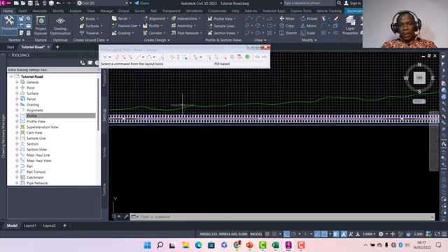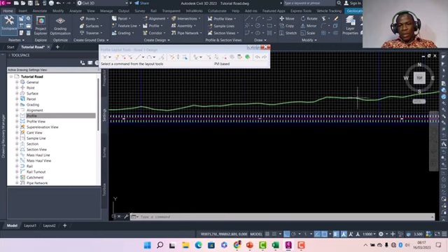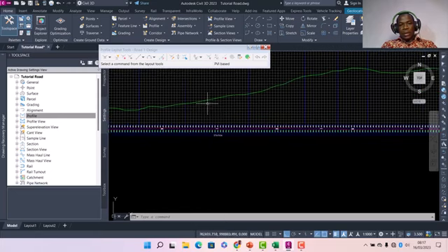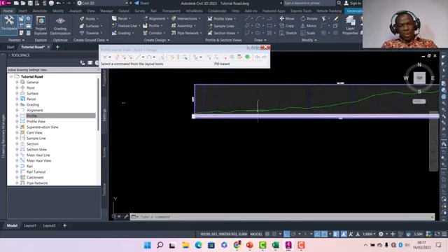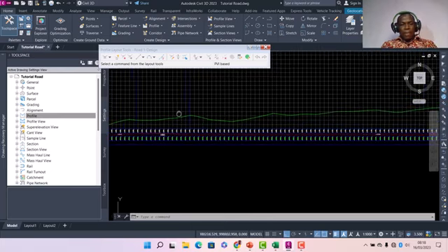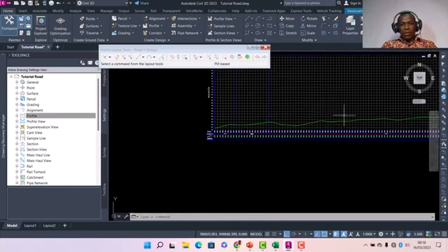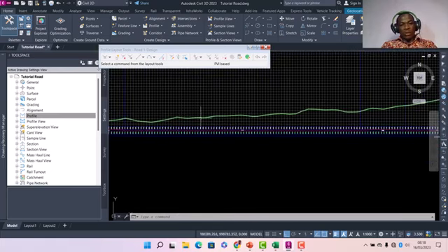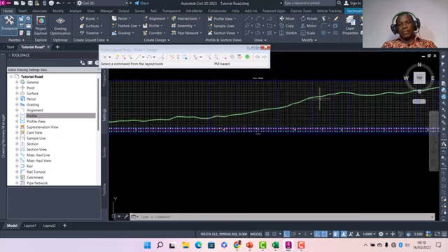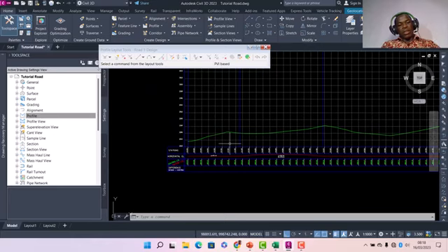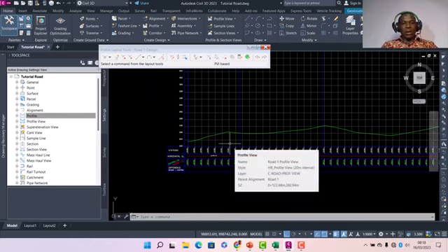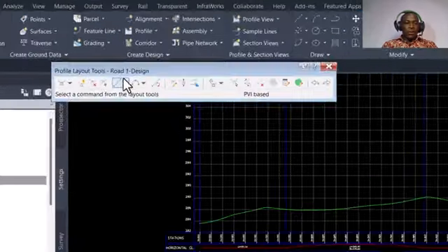Okay, and then maybe have a crest here, have a little sag here, and then start to take that up, and then you have the liberty to do that, but I just want to keep this simple. All right, so let me just keep it simple by having just a straight. I'll have a large cut and fill and then go down up to here, of course, watching that I don't go more than 2 meters in cut or fill. So let me check that.